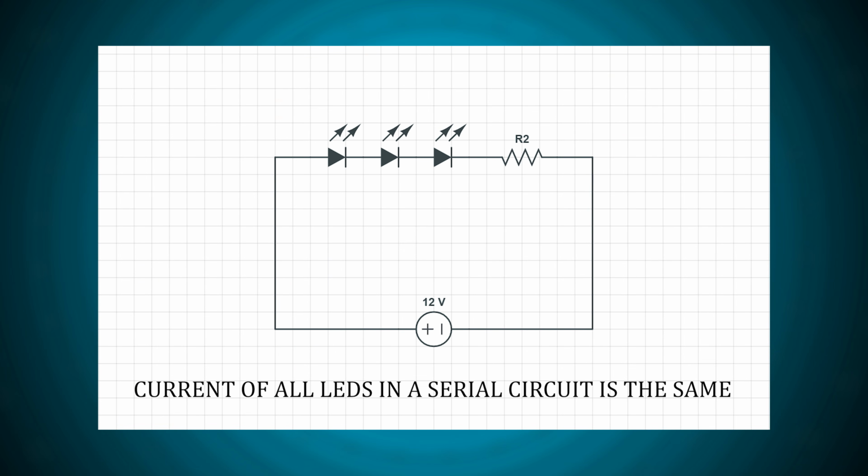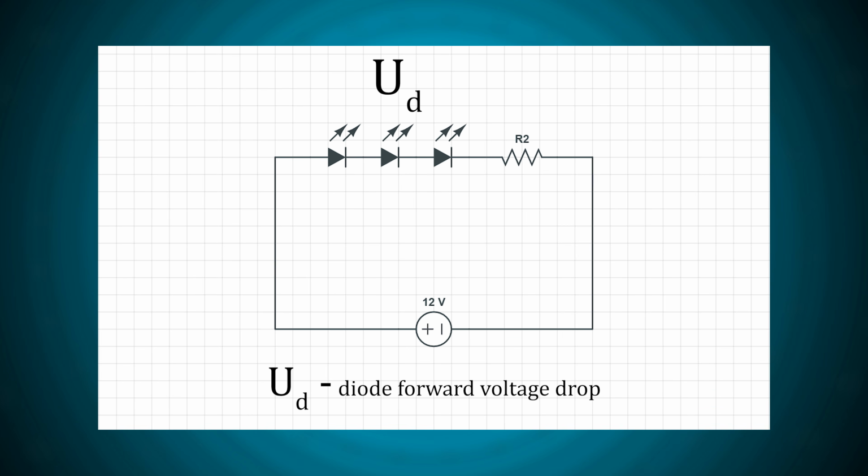The LED voltage drop is designated UD. It is also called diode forward voltage, and the diode, when it's on, is called forward biased. Safe LED current, in our case, is set at 60 mA, designated as ID. U is our power supply voltage and is equal to 12 volts. UR is the amount of voltage dropped on the resistor.